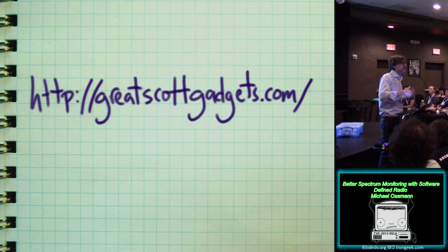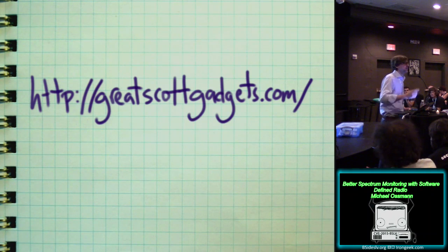We have some kind of a serial interface between the microcontroller and the synthesizer chip, and it takes some finite amount of time to actually give it a command. Just like it takes a finite amount of time to give a command over USB, but it's much less than the time it takes to give a command over USB. So those are the two limiting factors: the serial interfaces to control those synthesizers, and the lock time that it takes for them to lock into a new frequency.